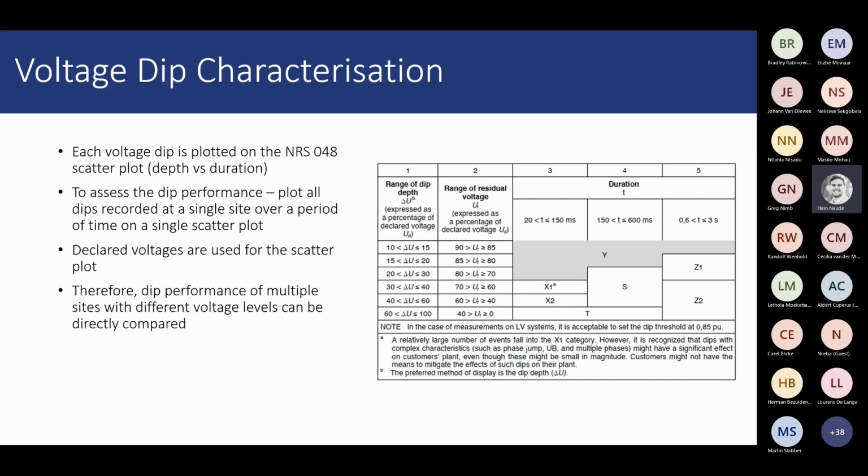necessarily. On your second question, Modbus TCP is standard on the Vector 3. So DNP3 and IEC 61850 are not standard. There are additional modules required to enable that. Modbus TCP is enabled by default. So my recommendation would be to use that if you want to interface.